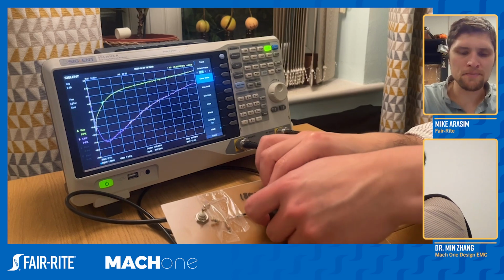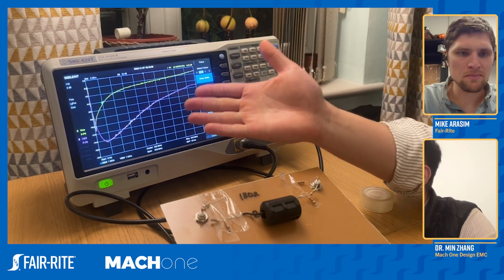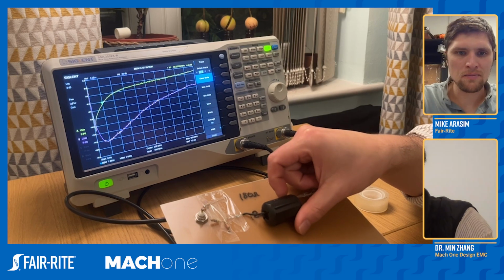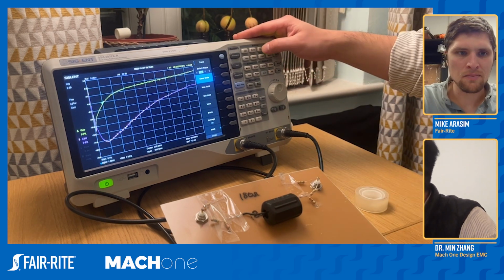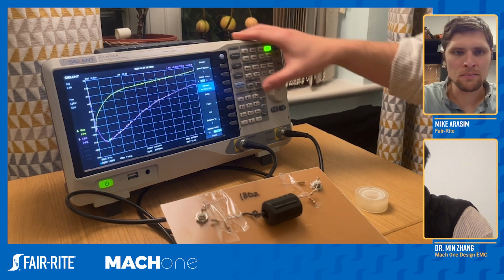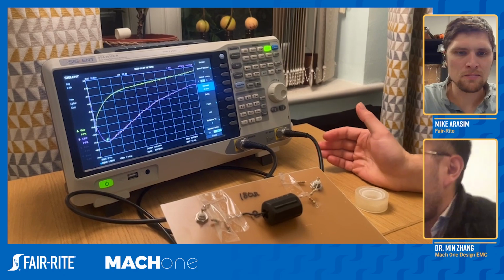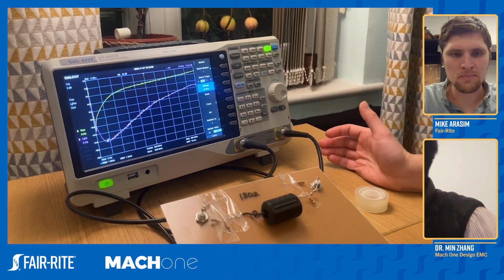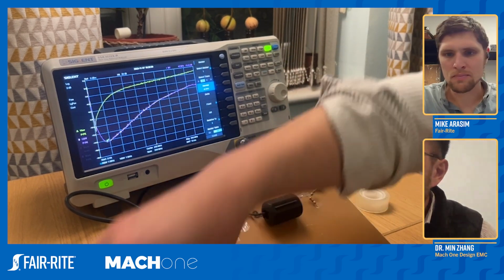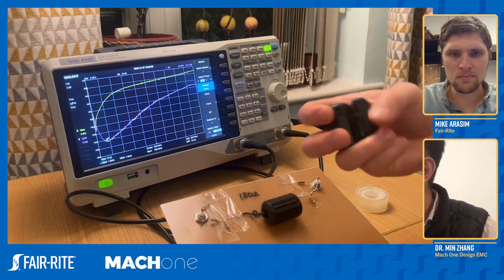As you can see here, I place a ferrite core on this cable, and I can see the insertion loss, or attenuation, against frequency. This is a 31 material I placed, and using a marker function I can see that it's most effective at about 40 megahertz. At 40 megahertz, it gives me about 14 dB attenuation, and I can easily swap different ferrite core materials on the same wire.